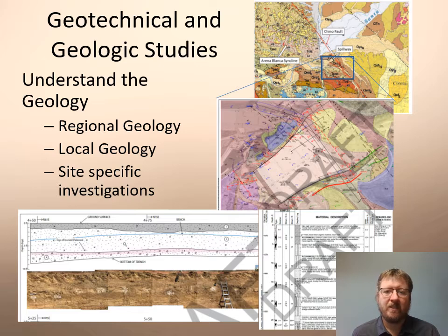Typically, geotechnical and geologic studies start with desktop studies and work their way from a regional big picture scale to site-specific investigations and analysis. Here, you can see we start by looking at the regional geology maps. We make site-specific geology maps, and then we perform investigations to understand how the site-specific properties of different materials will impact the performance and the design of a project.